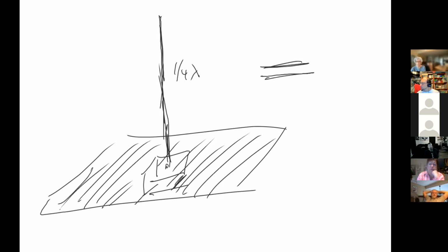And why does that work? Because we are talking about very high frequency AC. And what does a capacitor look like with AC? It looks like a short circuit. So basically that flows current into the roof of the car, and the roof of the car mimics the other half of the antenna, which is also why if you have a fiberglass roofed car, it doesn't work. So the other cool thing is that if you take this antenna and you just make a quarter wave like this.